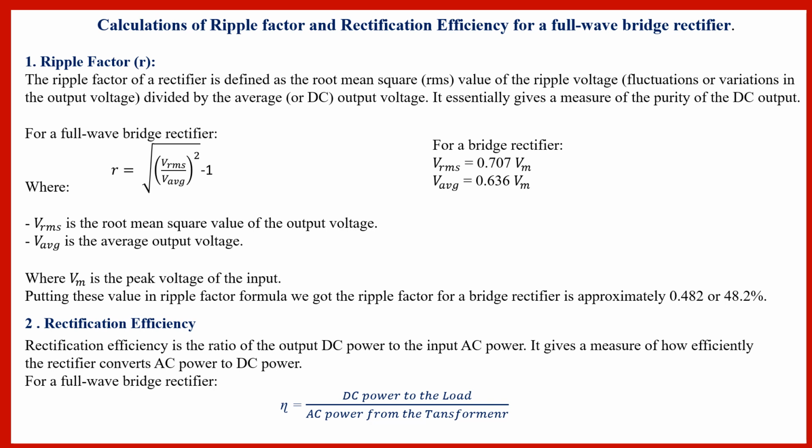it consists of the DC component and AC component. Because if we talk about a rectifier, it converts AC into DC. So at the output, you should be having the DC. But apart from DC, we have some part of AC in the output. That particular AC component is known as the ripple. The AC component is undesirable, that we don't want, and it accounts for the pulsation in the rectifier output.